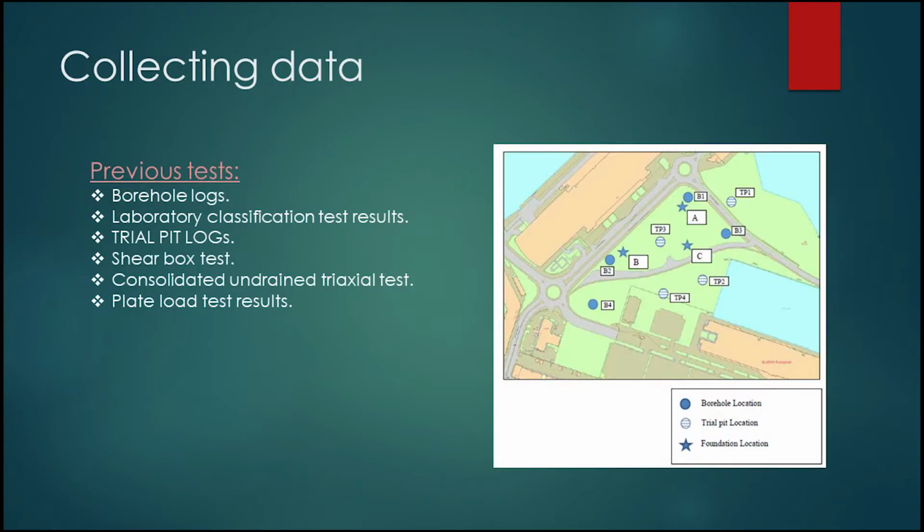In this part, I'm going to talk about the planning of dimension foundation. First of all, we took all the useful information from the project. From this data, we have drawn the necessary curves for the study of our foundation with the different depths. We determined that depth of the foundation equals 3 meters because we have clayey sand and the project is near the sea.